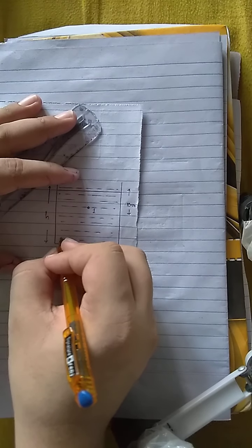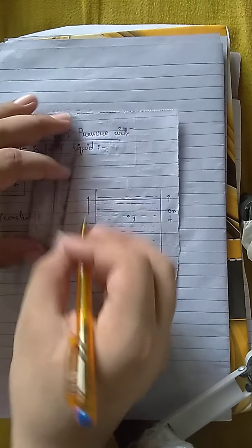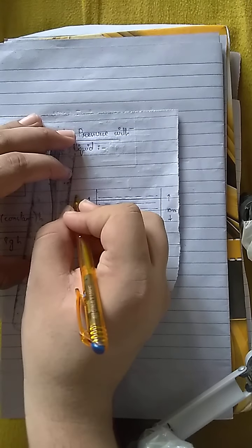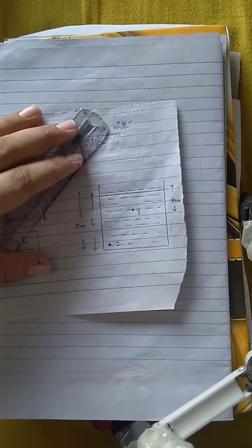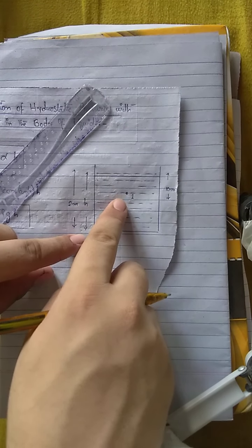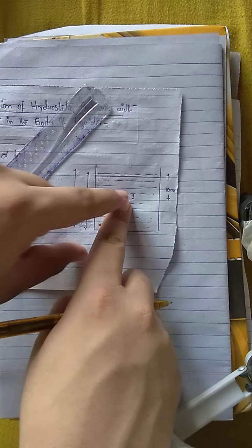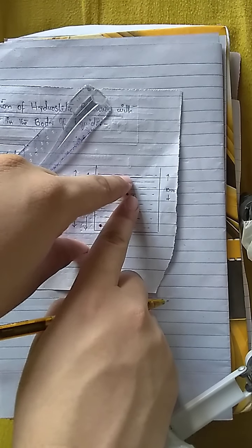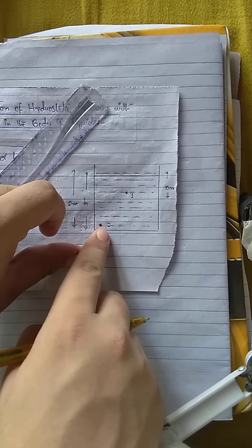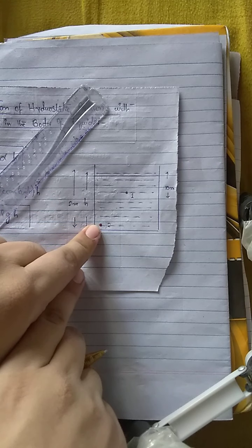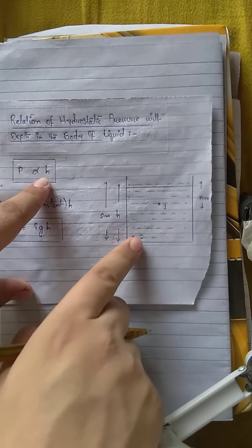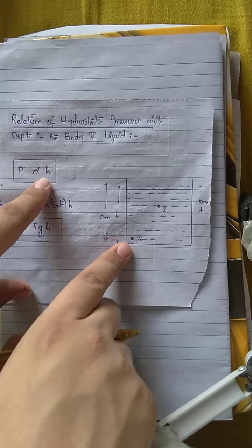and there is another point, say point 2, lying 2 meters from the surface, then obviously the pressure at point 2, which is exerted by the column of liquid above it, is much less than the hydrostatic pressure at point 1. So the hydrostatic pressure is directly dependent on the depth inside the body of the liquid. The greater the depth, the greater the value of hydrostatic pressure.